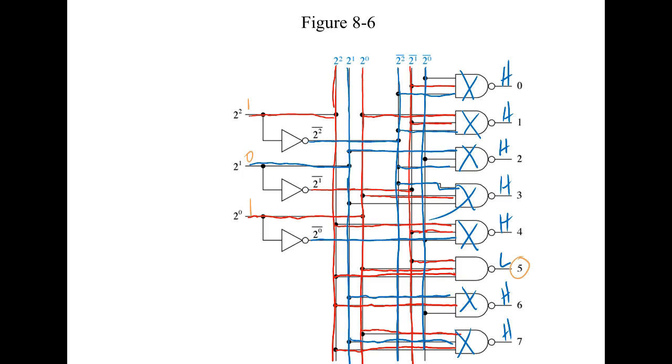So this would be what we call a 3 to 8 decoder. It's also called a binary to octal decoder. 74138, and then the different versions of it, right? Or family. So we have a 74138, we have a 74L138, we have a 74H138, we have a 74F138, we have a 74LS138, we have a 74ALS138. So what's the center letters telling us?